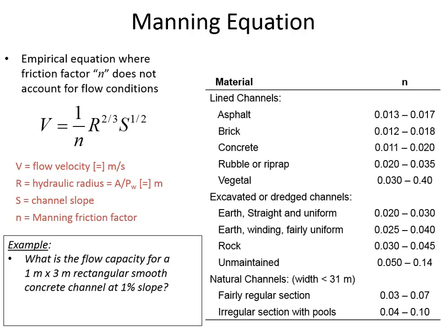And then we have a rectangular channel where the bottom width and the top width are both equal to 3 meters. So B equals 3, capital B equals 3 meters. Because it's rectangular, they're equal. And then the flow depth, Y sub N, is 1 meter. Now, the actual conduit may be taller than that, but it doesn't matter to us because the only thing that's relevant for calculating the flow rate is the flow depth rather than how tall the channel goes.